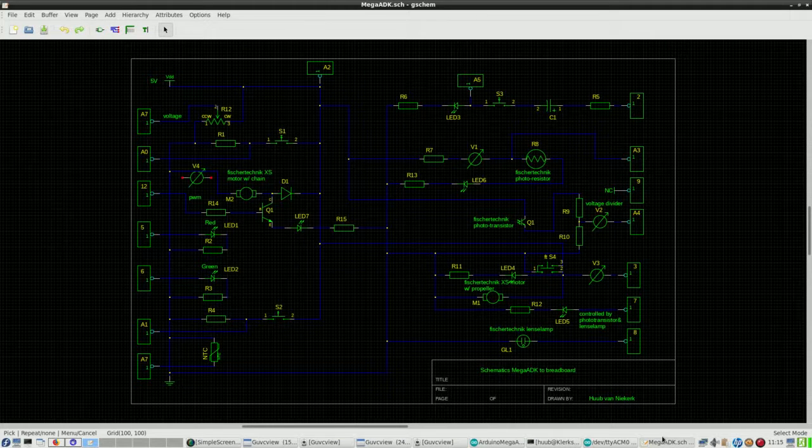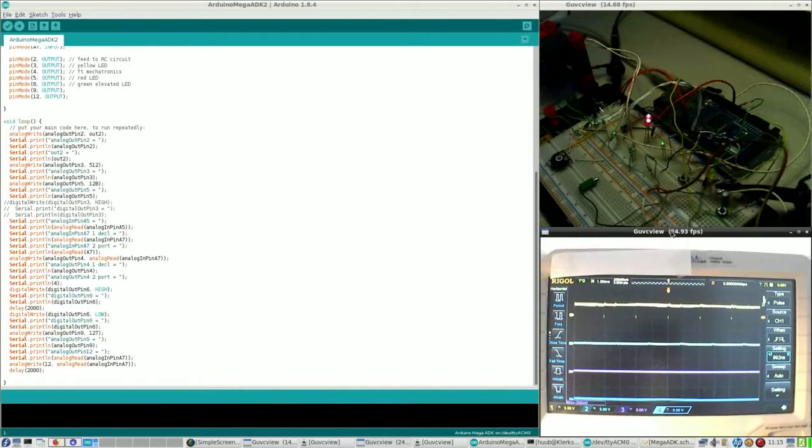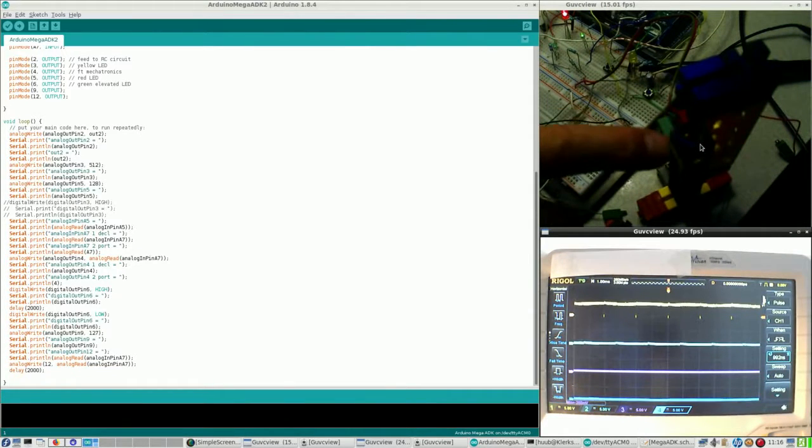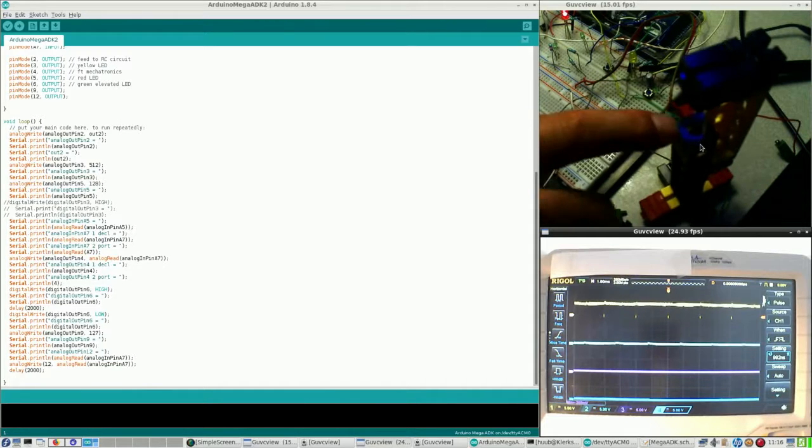So where does the voltage divider connect to, apart from the phototransistor, which basically is a binary switch, so it is either 1 or 0. It connects to A4, and indeed A4 was blank, was empty, so I reconnected it, and it is connected to this voltage, to this phototransistor right here.